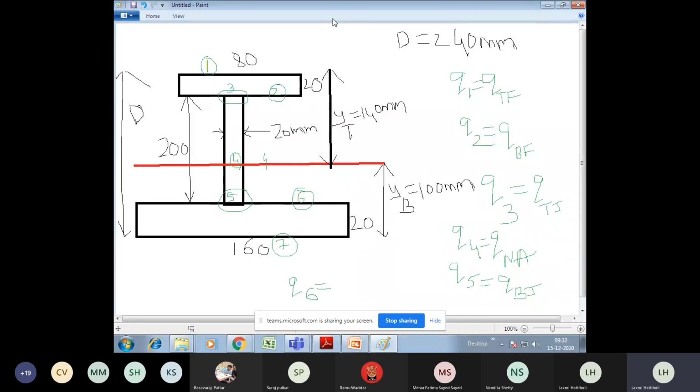Of course, while understanding it, maybe you are feeling a bit difficult, but while calculating, I'll tell you what is the smallest difference you need to do. So it becomes very easy to understand. Before I go to the calculation part, let me repeat where you should calculate the shear stress, and let me tell you a few thumb rules. First of all, you know that shear stress is maximum at the neutral axis and it goes on reducing as you go to the top or bottom fiber.